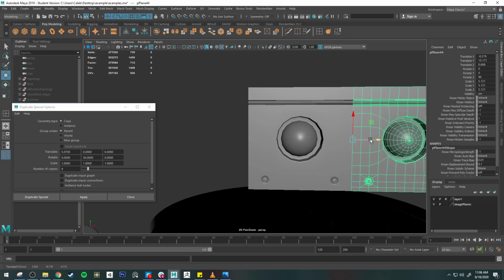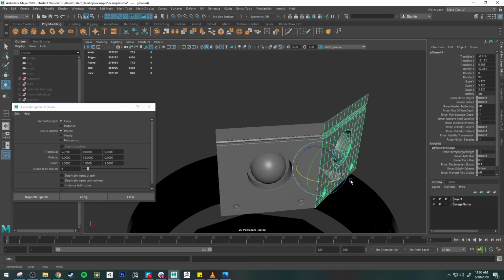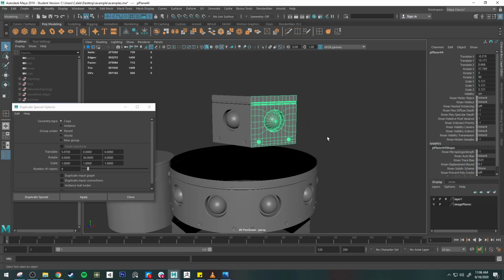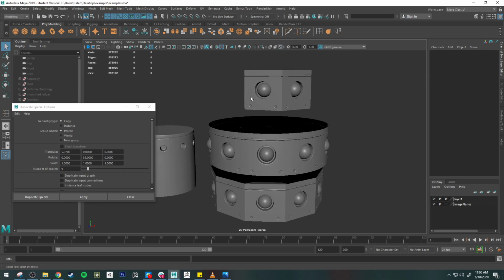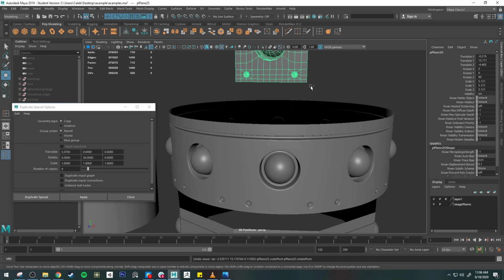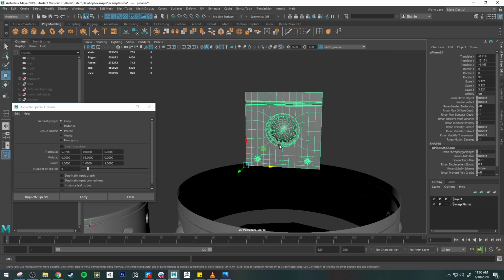So I'm going to move it over here, and then I'm also going to rotate it, right? I'm going to rotate it like that. By having that pivot point around that edge right there, it's going to shift over, and then it's going to act like a hinge and rotate like a little panel, okay? So that's what I did there. Let's just move that pivot point up. I'm pressing D to activate the pivot point and holding V to snap the pivot point to a vertex, okay?